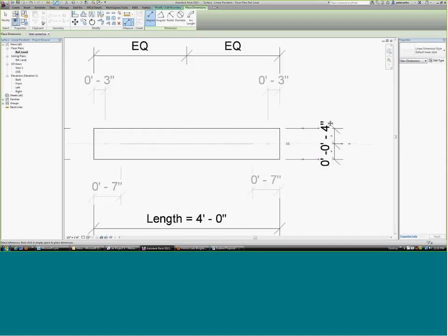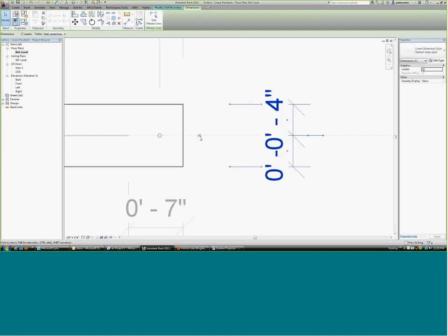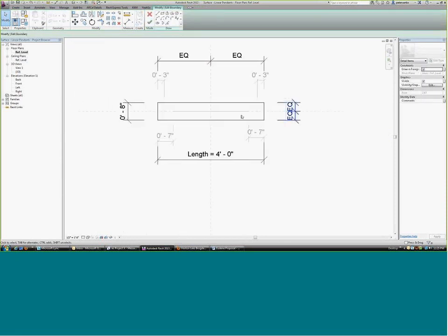If a dimension is black, it means that it's controlling things. So I laid down a series of dimensions. I'm going to make those equal so that it always grows and shrinks off of the center line. Black versus grayed out. I started a dimension. I hit the reference plane first. I hit tab until I touch reference.